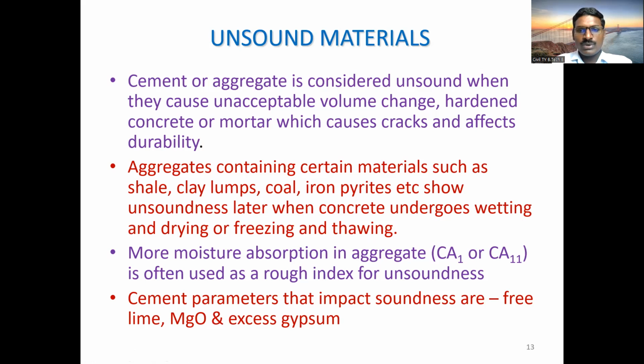Whatever water we are adding into the concrete, the maximum water absorption of the aggregate should not be greater than 2 to 3%. 2 to 3% पेक्षा जास्त water aggregate ने absorb केलं नाही पाहिजे. If the aggregates absorb the water, then the quality of the concrete will be low and the durability of concrete will be affected.